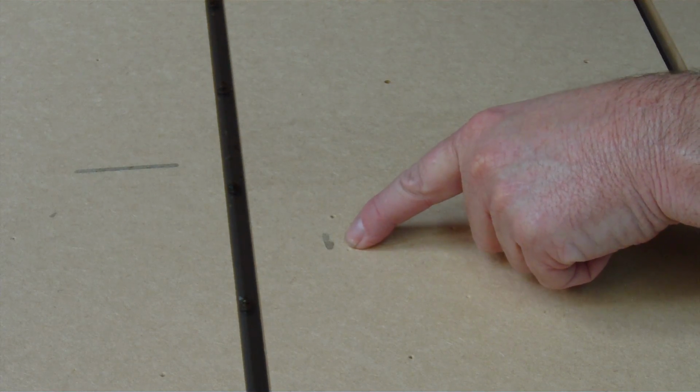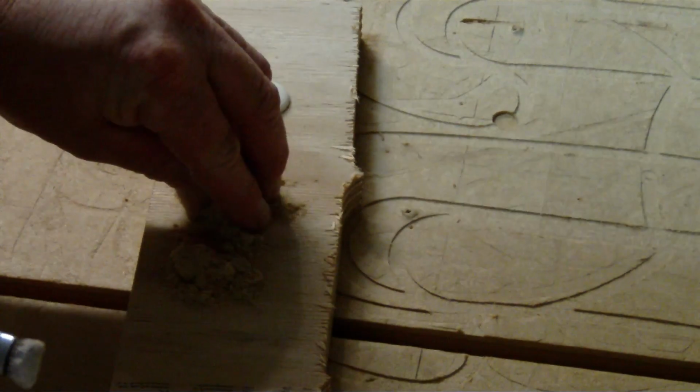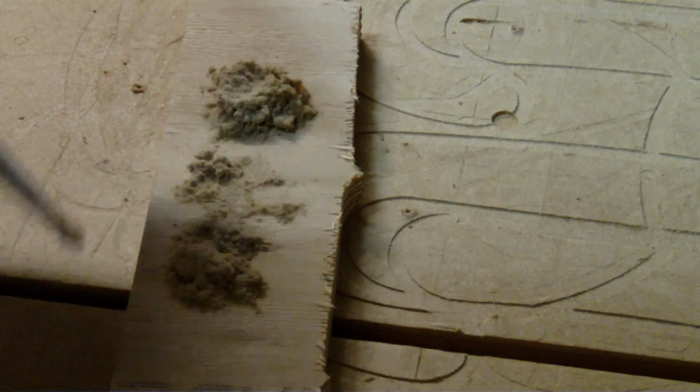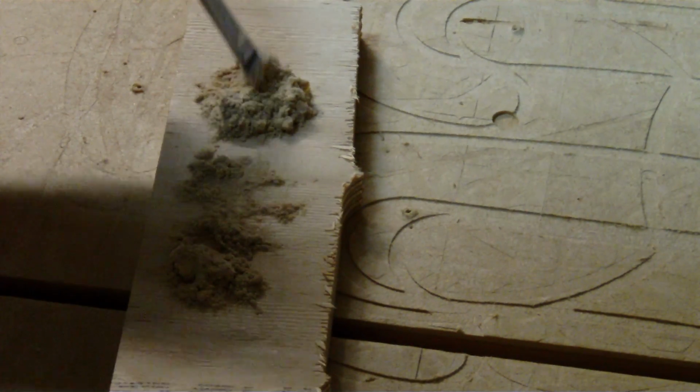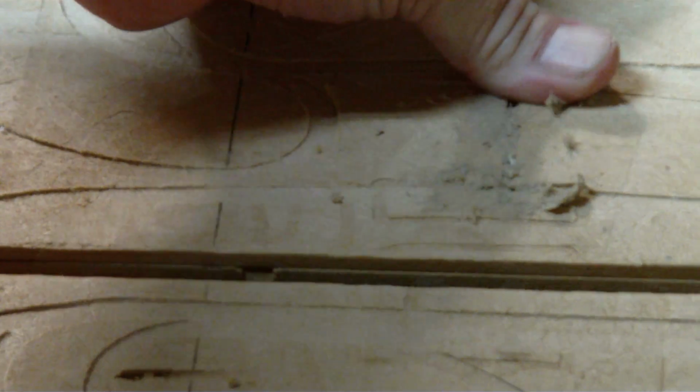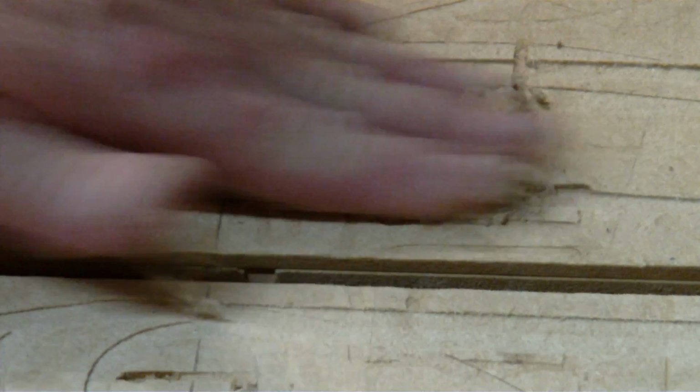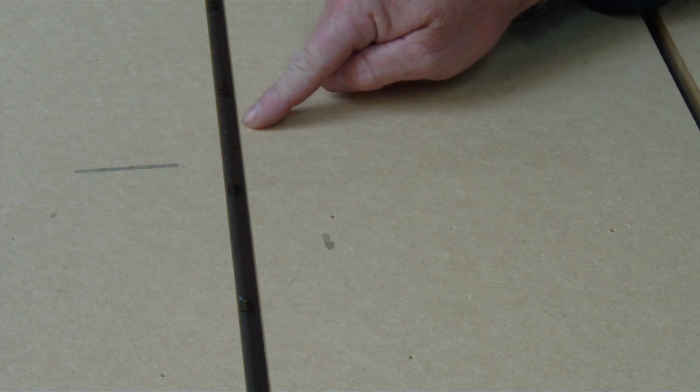These were just those grooves I mentioned earlier in my previous video, and I filled these using a mixture of just MDF dust and PVA glue. I just mixed it up as a paste, put more glue in the hole, and just pushed it into those cutter holes. Here is a repair that I did last year. It's only visible because the MDF is just slightly different colour to the original board.